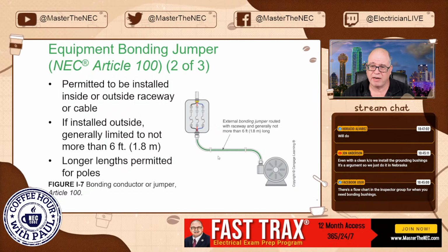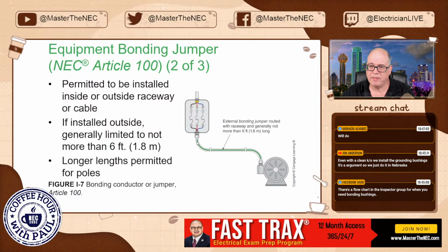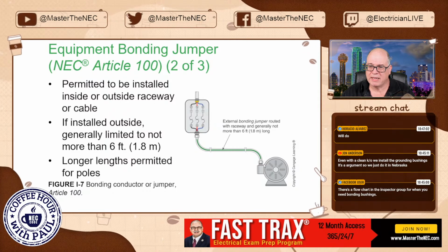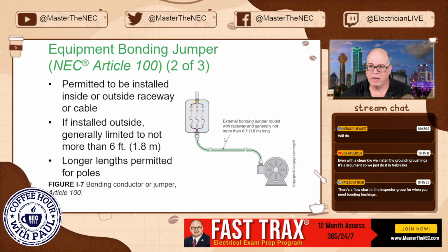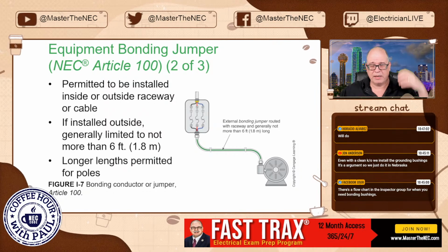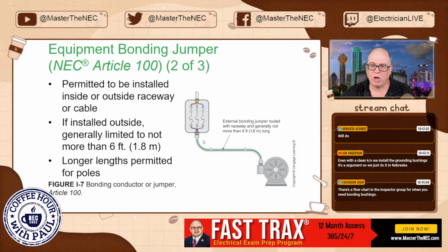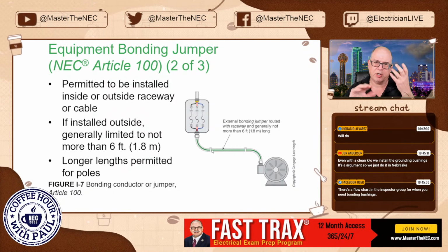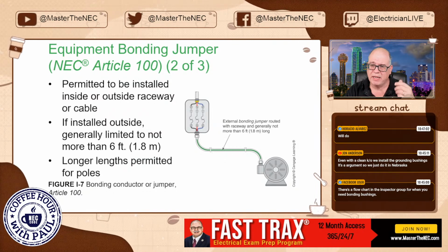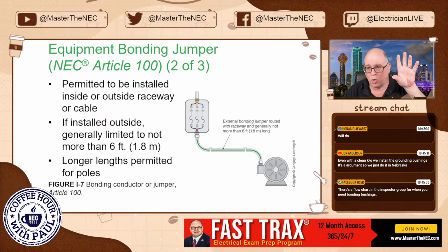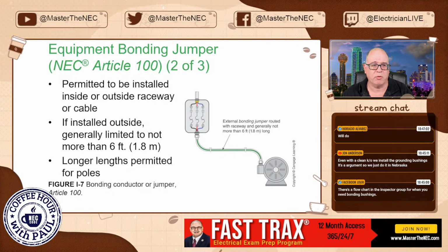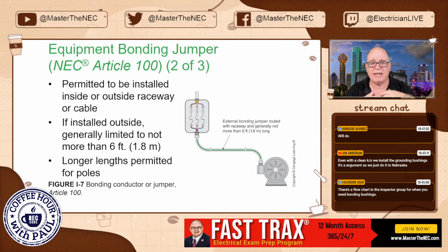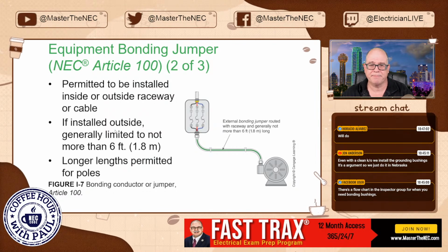The other thing with this right here is to remember that this is making sure that the potential from here to here is the same, okay? They're at the same potential. And if they're close, the one other reason that we like to put equipment at the same potential, if they're metal, is because you could be able to touch one to the other. And the last thing we want to do is create a path that can go across the most volatile portion of our body, and that's across the heart, okay?